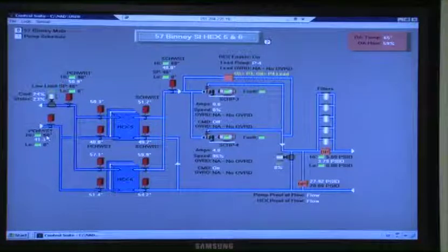Is that the set point? Those are alarm set points. Alarm set point. So we have high alarm, low alarm, and it's maintaining what it's maintaining. See right below 57 on the top? That's your set point up there for the water. 60. Up here. Yes. So this here, we're trying to maintain a set point of 48 degrees over here. So we're trying to maintain 48 degrees, that's our set point, of processed chilled water to the MRIs.